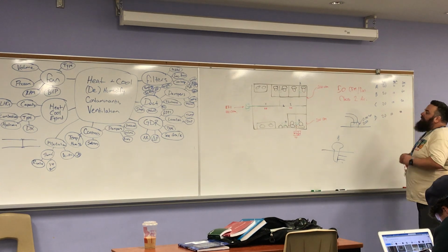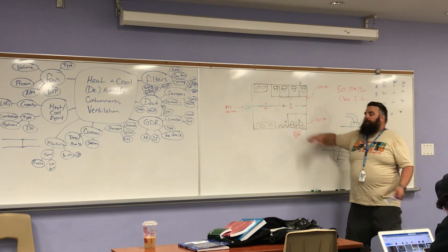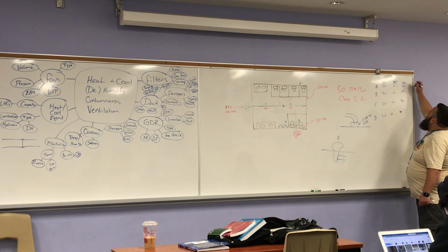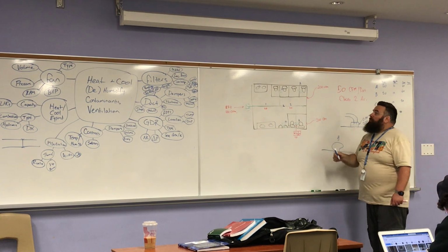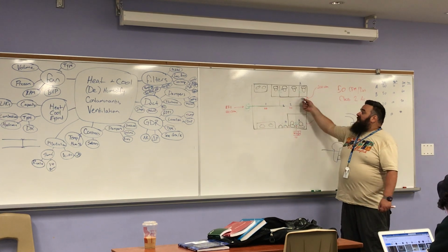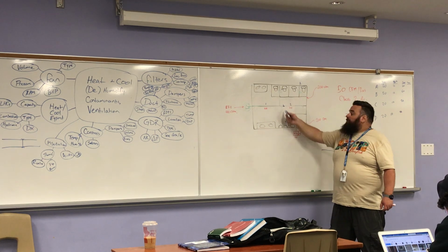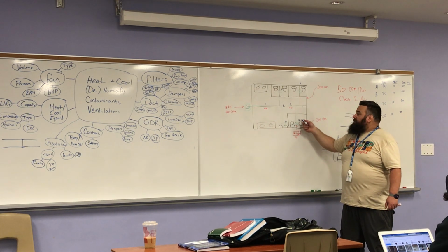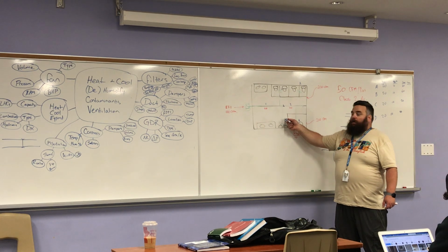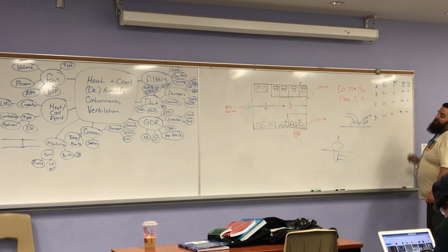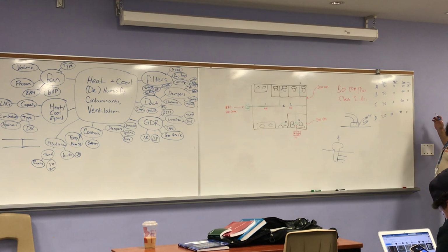But the point is, everything's a little bit different, right? And I'm going to add here, let's say, transitions where the duct gets bigger. Let's say that's 15 feet. Does A have a transition? Yes, because the air from A has to go through that fitting. How about B? Yes. D? No. And C, no, right? So we're only giving A 15 feet, B 15 feet, 0 and 0 for the others. And we do this across and so forth, okay?